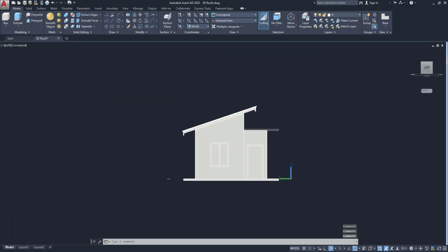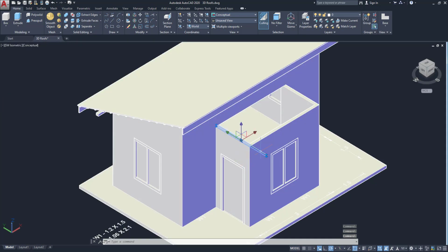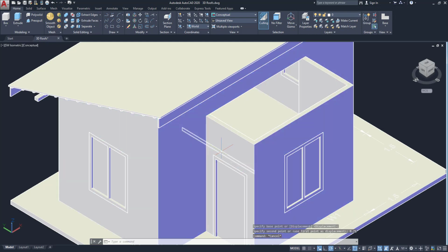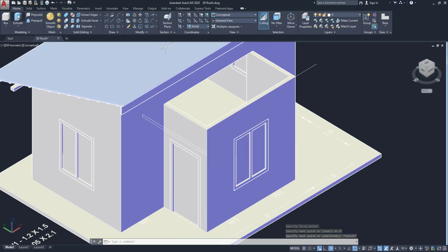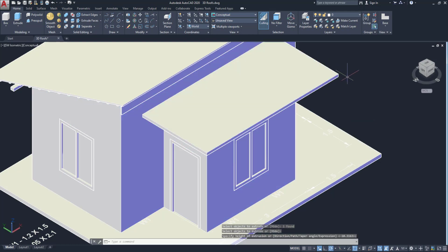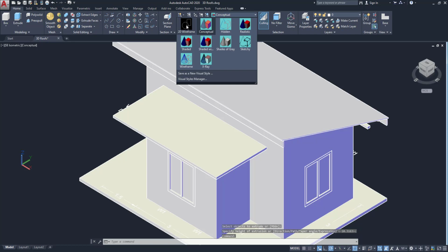Now you can go to left view, then you can see this so nicely placed. So go to this view, move, place somewhere on here and go to 0.75, enter. This is our slab. You can extrude this slab from here to here, so 0.75. Pick this point and go here, 0.75, enter. Up to this we have to extrude. Click on the extrude button, select this object and enter and place this. Now it's already created. So you can change the view to see all the objects.